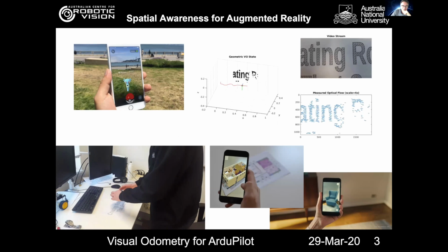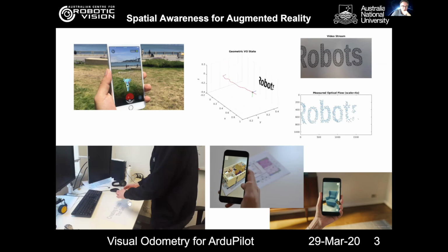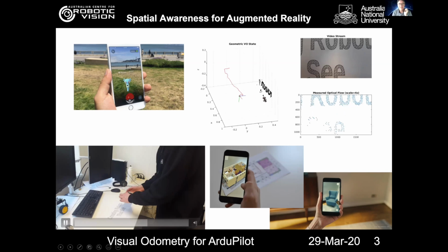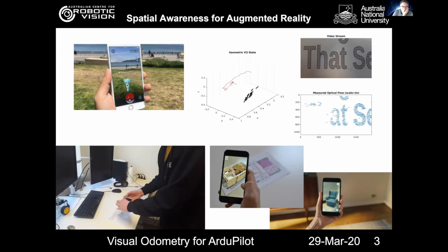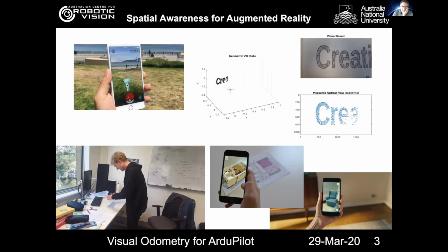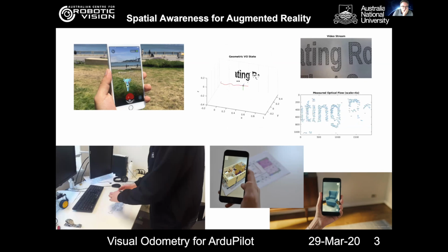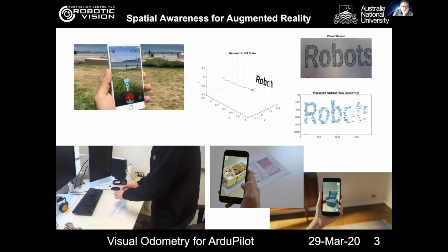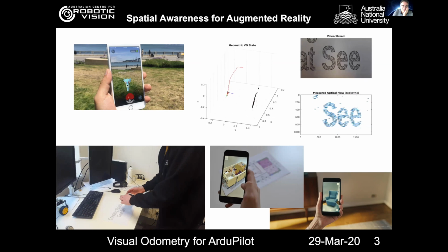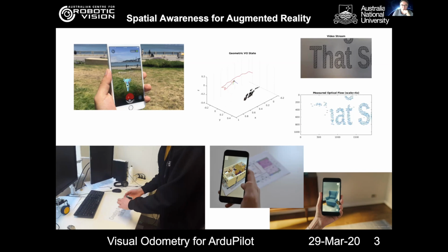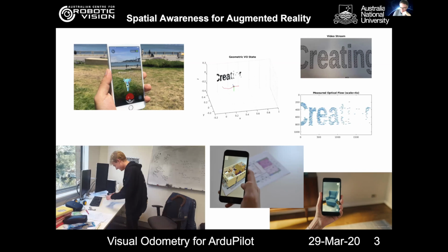This is just a demo of some work by Peter Van Goor, my student, who'll talk a little bit later and show a demo. This is your classic visual odometry problem. You're using a camera, in this case just on a phone, looking at an object and seeing points, which you can see in the top right. From measuring the points and looking at the way they move, it's recreating the actual trajectory of the robot moving through space. If you think about this from the point of view of scale, here we're quite small and quite close to what we're looking at. But if you multiply all of the scales by 10, it would be very similar to a vehicle flying over some relatively flat surface. That's the algorithm that we'll at least show to you.